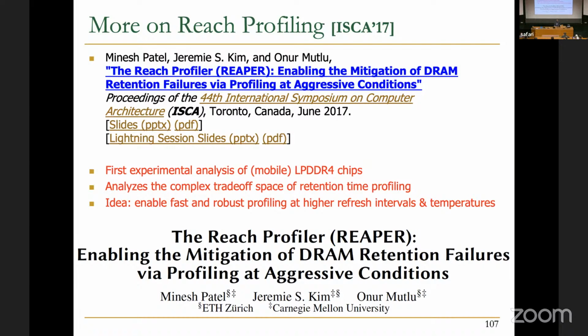Any other questions? Maybe I can make a quick comment about that as well. In these works, we don't see that, but if you look at the recent literature about RowHammer mitigations, the latest update in DDR5 that Nisa will mention suggests that you keep how many times you activate a row as metadata. You keep that activation count inside the DRAM array, which is also actually susceptible to RowHammer, but you also protect that. So you need to ensure that reliability. But I think there are multiple ways of storing that metadata.